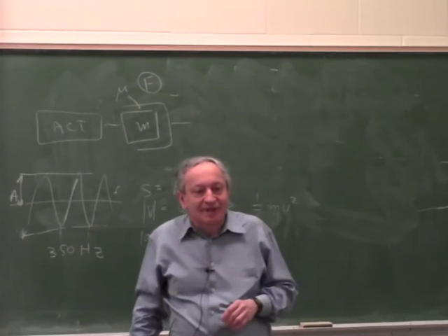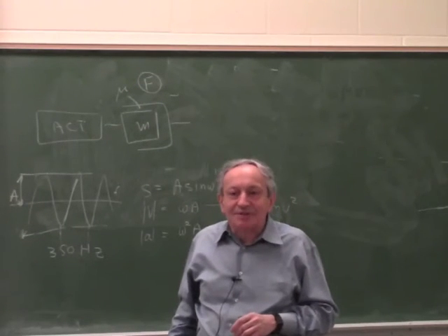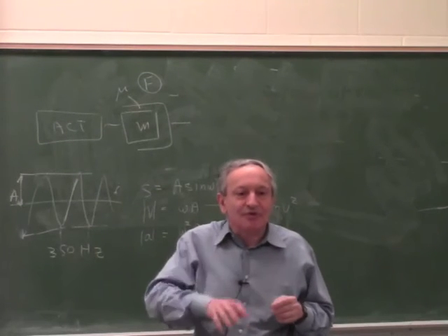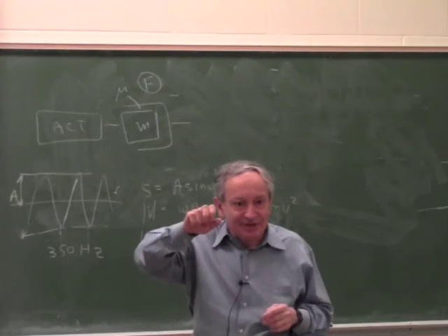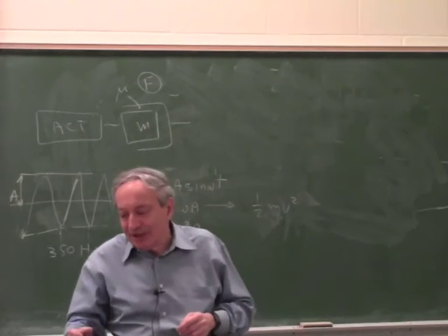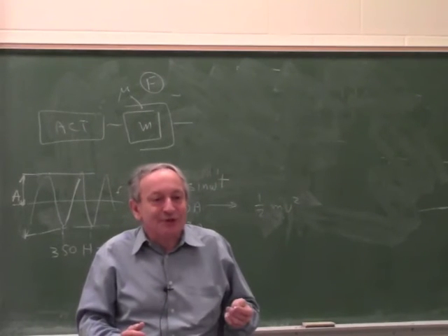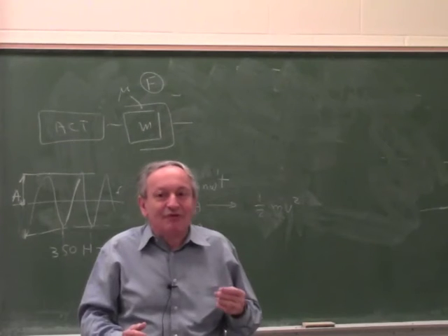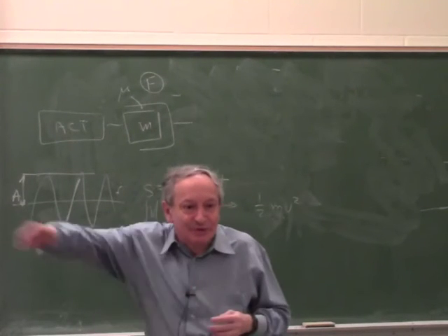Even if it wasn't recoverable, don't you still need the same power to get to that point? Yes, but if it's recoverable, when you move a mass in a servo, the first part you accelerate and the second part you brake. If it's recoverable, the braking energy is equal to the accelerating energy, so it should need no energy. Because for every acceleration, there has to come an equal braking. Otherwise, it will go away forever.